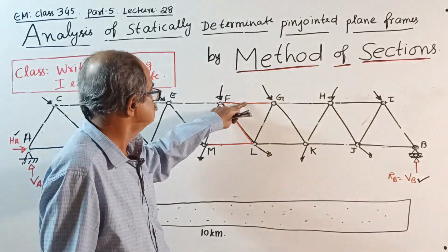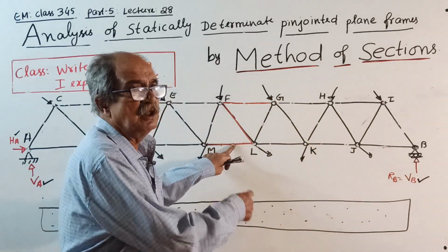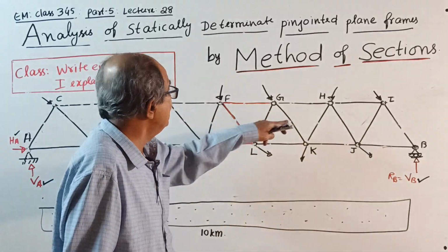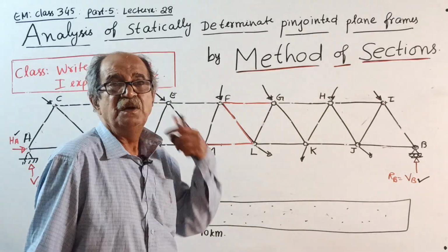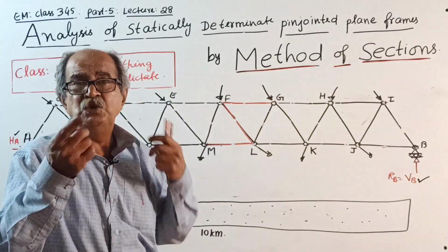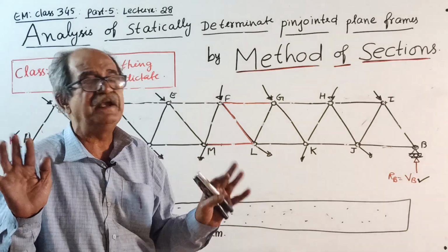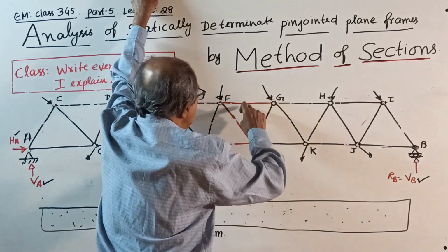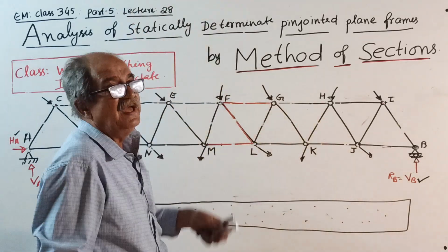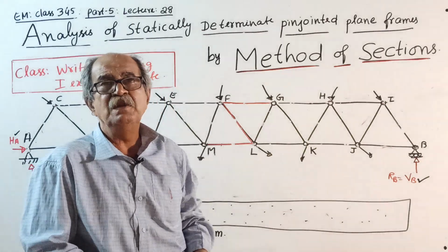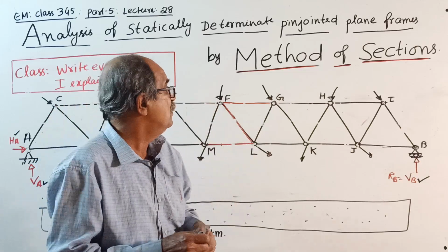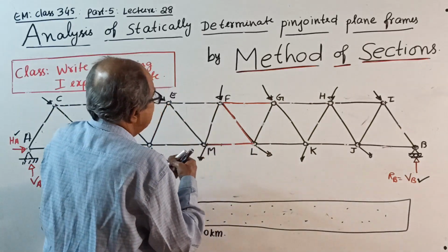Compression. This member depends on the loading also. Tension. This member. I will think a little and tell this force. But there is difference between you and me. Sorry, you have to admit it. It is difficult. See, so many in between. Difficult. Therefore, what I do in method of section is, I will always assume member force to be tensile in